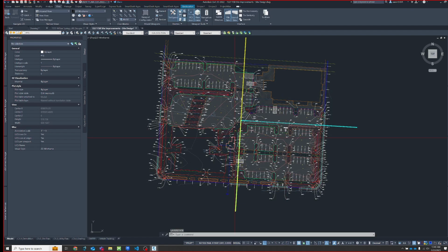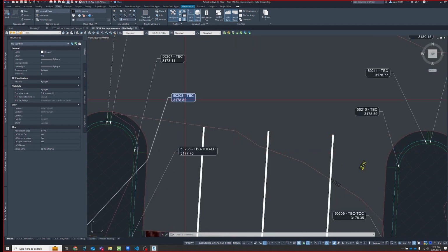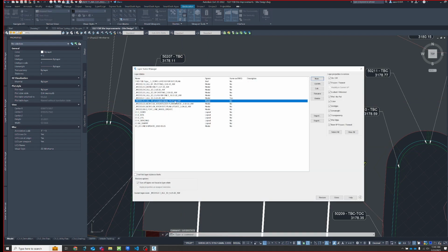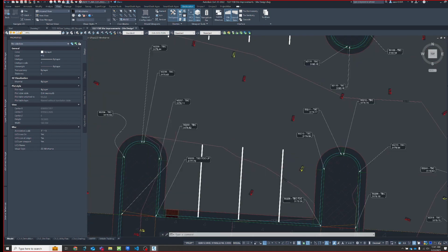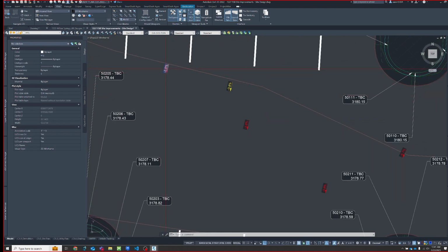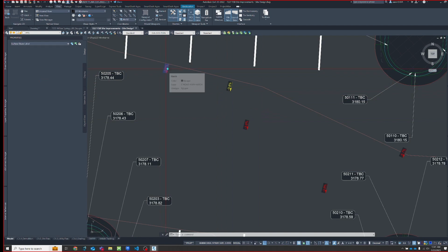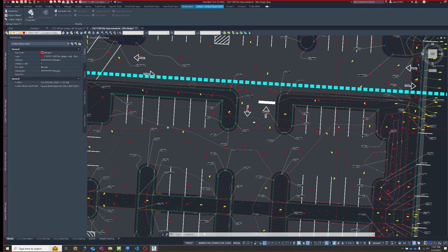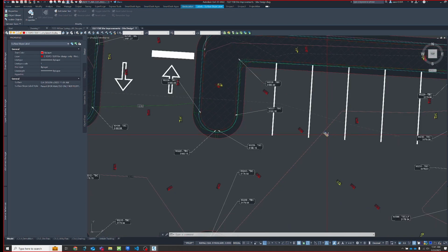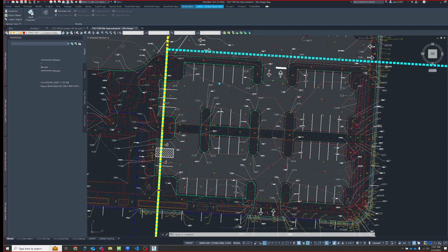And maybe I have certain labels turned on and off to be my final presentation labels like these. And maybe I have a layer state, and this one maybe gets a little carried away, but I had so many RFIs on this project, it kind of made sense as I just kept taking on RFI after RFI. This one just turns on a couple of layers with a lot of analysis slope labels that I don't want to plot, but I just put in a lot of spots to quickly catch trouble slope areas and to fix in my triangulation of the surface.